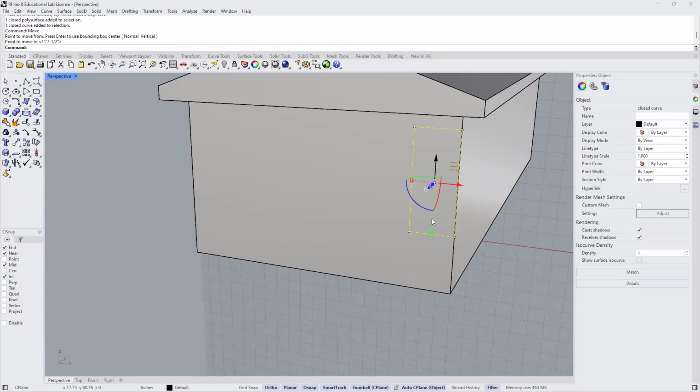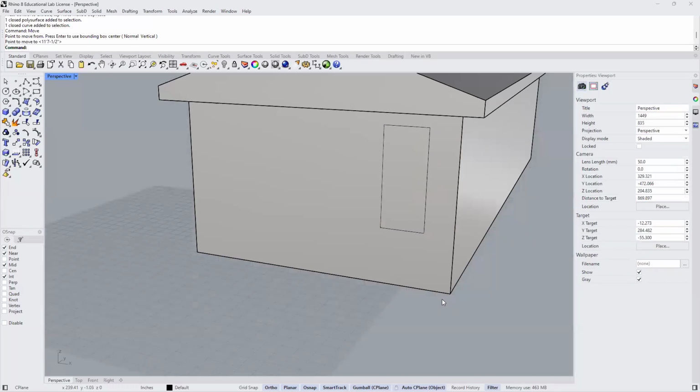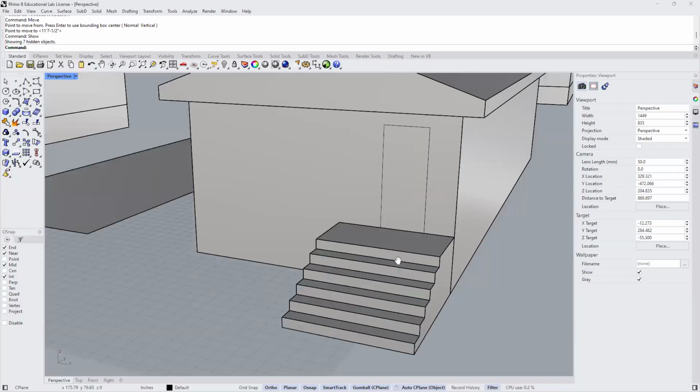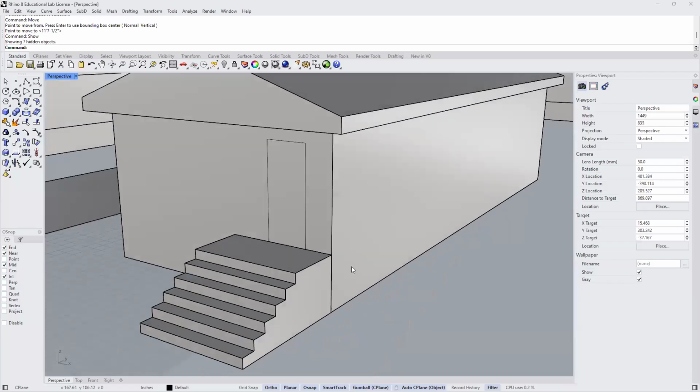And now I'd like to move it over at least 2 feet away from the wall. And you pick whatever value you want. So I'm going to click on my red arrow here. I'm going to say -2 feet, enter. And then I'll tap the escape key. And I'll go ahead and type show. And I do have that opening right where it should be.